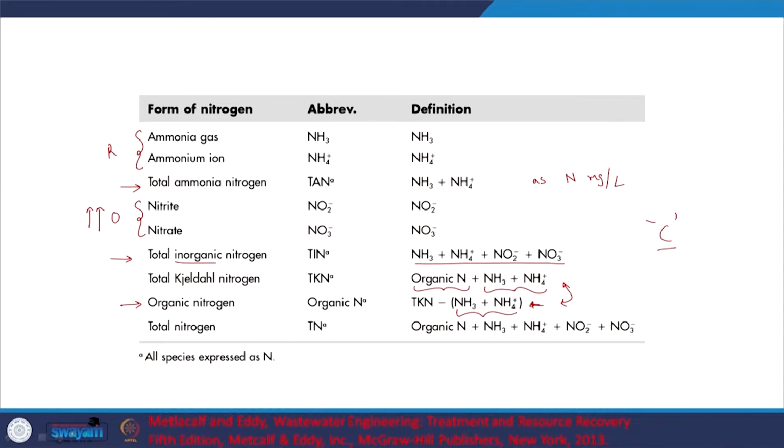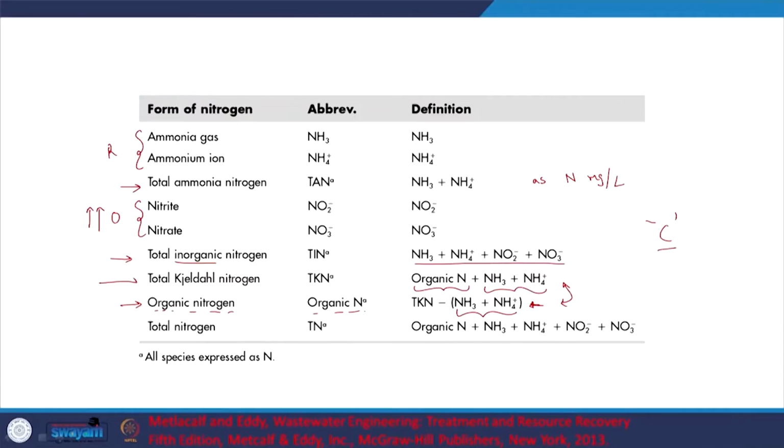Another aspect to look at is that when we are trying to look at organic nitrogen, we then digest this organic N, right. It is bound to the organic compounds. You want to break these bonds, and you typically look at digestion by applying acids and maybe some heat, let us say, right. So, that is something to keep in mind. Typically, we are concerned with TKN, right, TKN.